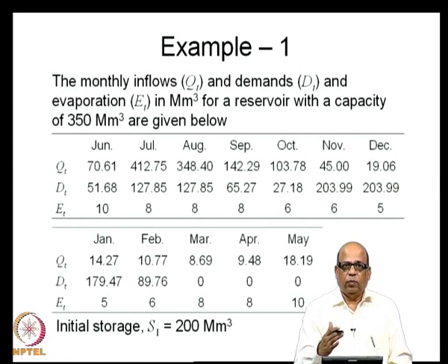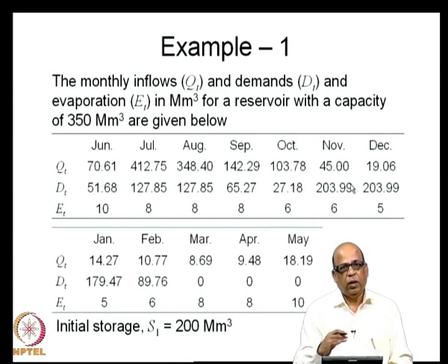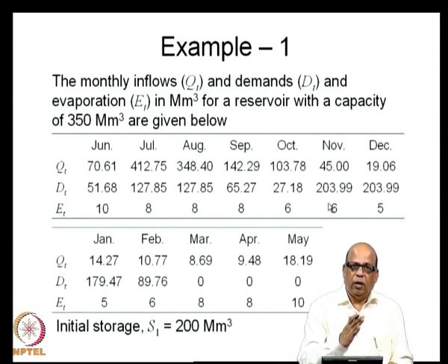Like this. So, there will be a period typically in monsoon regions like ours. After the monsoon is over, your flows will start reducing. In fact, they approach 0 very fast in most of the rivers, but the demand will start increasing because that is the Rabi season where the irrigation demand will be higher. So, this is the typical picture where the flows are smaller, you have large demands, and this mismatch is actually managed by the reservoir.